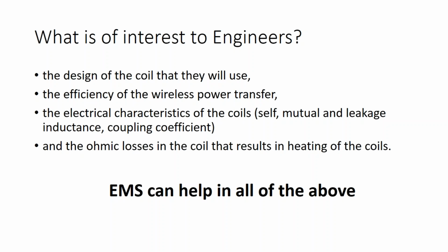Then one might be interested in the electrical characteristics of the coil. What are the inductances of the coil? What are the self, mutual, and leakage inductances? What is the coupling coefficient between the two coils, etc.? And finally, if there are any losses as a result of heating, the current losses or the ohmic losses in the coil, that might end up heating the coil. It's a good idea to understand that, so that we know for sure that the heat is manageable. In the case of wireless power transfer over small proximities, I don't think heat will be a big problem, but nevertheless, if that's of interest, that can also be studied using EMS.